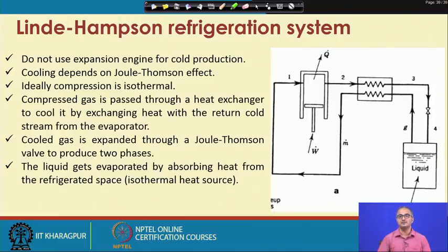So, let us first start with the Linde-Hampson. Both the Linde-Hampson and the pre-cooled Linde-Hampson use only the expansion valve for cooling and not any other engine. That is why they have been grouped together. The Linde-Hampson refrigeration system, sometimes also called the simple Linde-Hampson refrigeration system, does not use any kind of expansion engine for cold production, and the cooling is obtained purely based on the Joule-Thomson effect through an expansion valve.